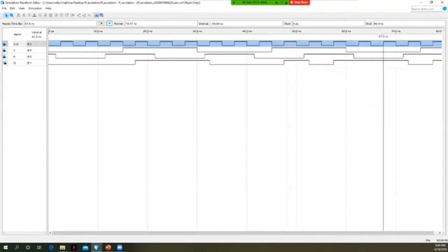Same thing there, it holds state. Same. Now here, K is a 1, J is a 0. We have the reset condition. In this case, K actually causes the reset. Q goes from 1 to 0. So by playing with these waveforms a bit, generating some of these different combinations, you can then see how the JK flip-flop works.